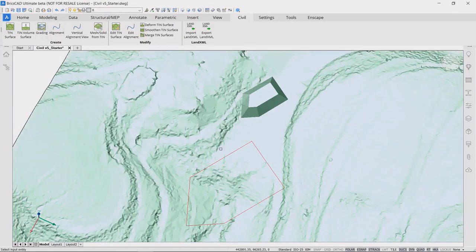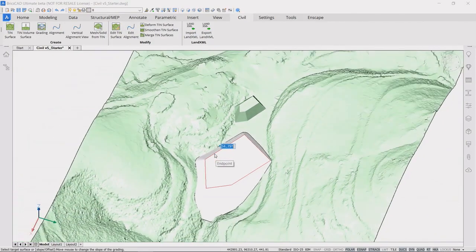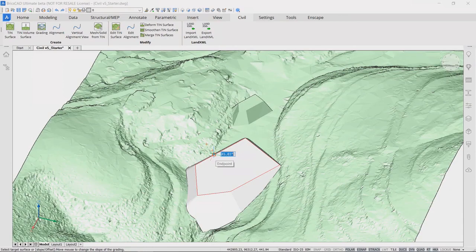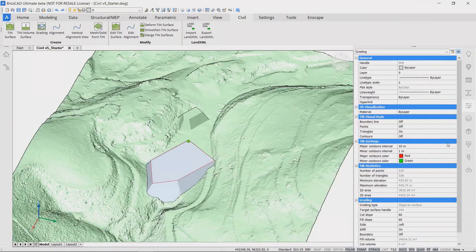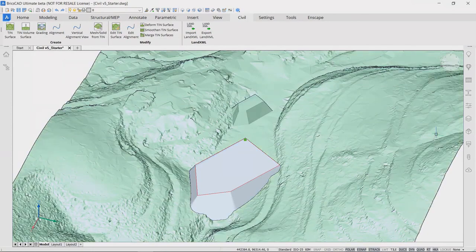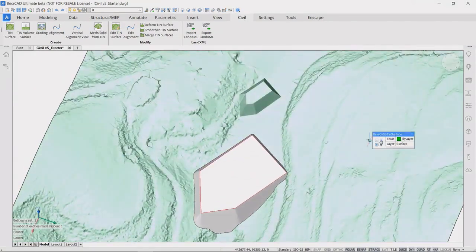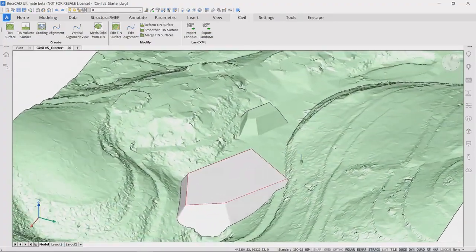So this is very handy if the outer and inner boundary of the building pad is defined and shouldn't change. But when we know the one footprint, and we know the slope, then we can use the grading technology. The grading technology helps you to create the side slopes with a certain angle to find the intersection to the existing ground, and such, let's say, irregular geometry is created.